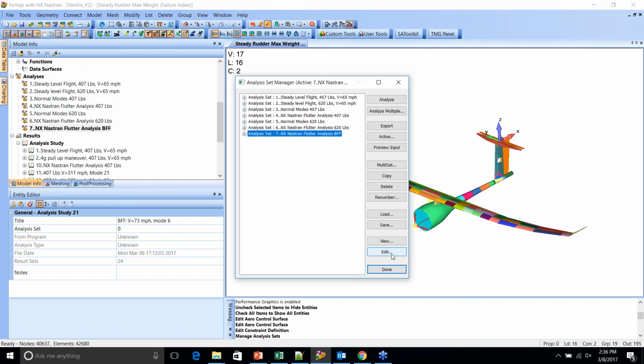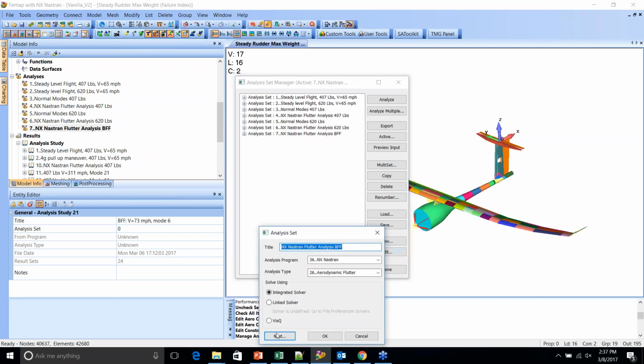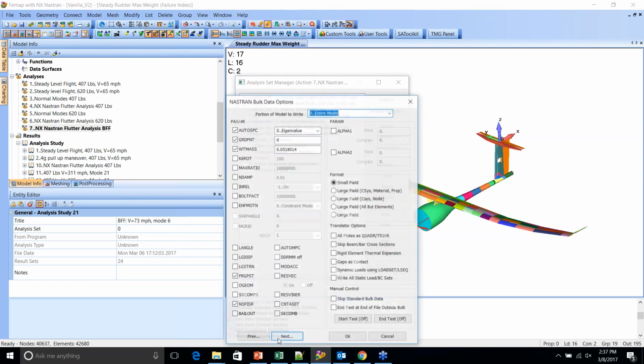So in order to make sure that you guys could see that, I went in and tweaked our model a little bit. And effectively what I did is I increased the mass weight parameter. So really what this is, I'll give you just the numerical representation, is 20 over 386.09. So normally you put 1 over g in this case to be consistent with your units. So effectively what I've done is I've scaled the mass up by 20 times, okay?